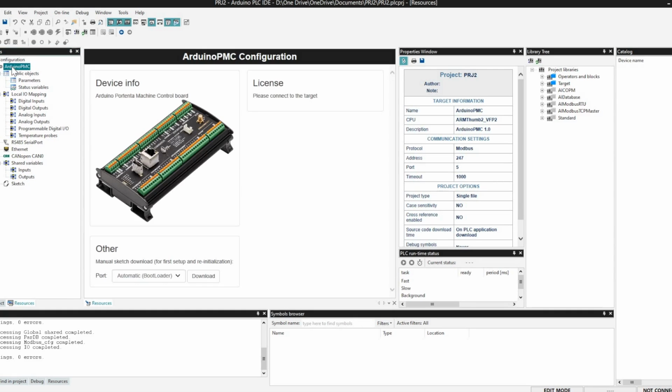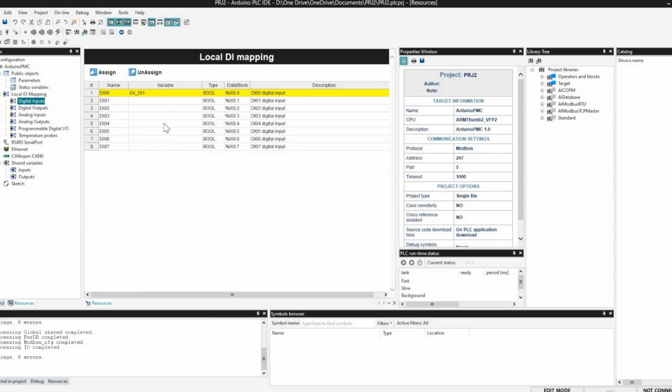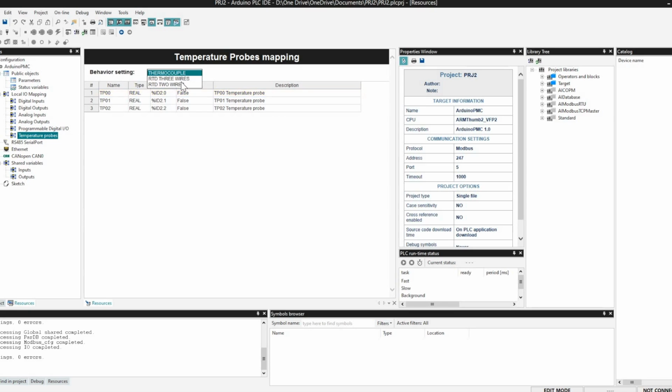So the different hardware options we have are the digital input, digital output, where we can configure analog input, analog output, configurable digital input and outputs, and thermocouple. So these are different options for each module you will get. For analog output we don't have any options, but for thermocouples we have three options here. RTD is also supported, thermocouple is also supported for the temperature part,